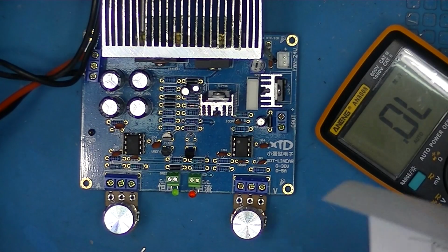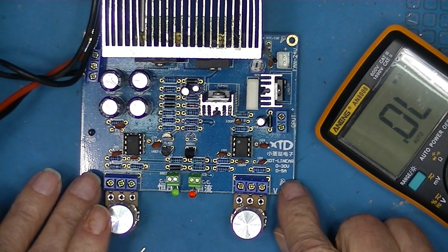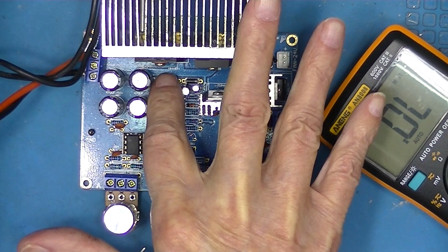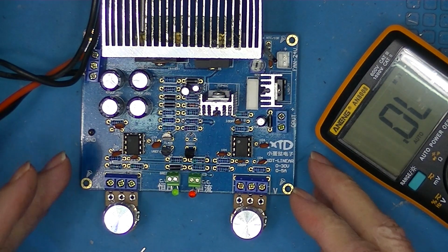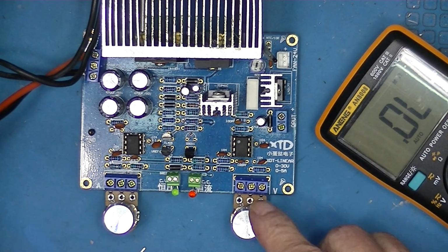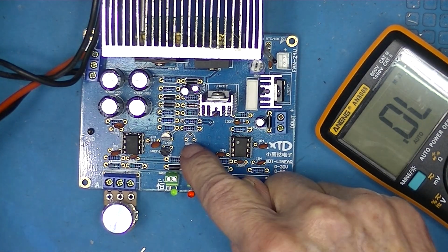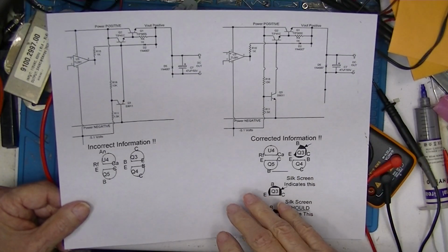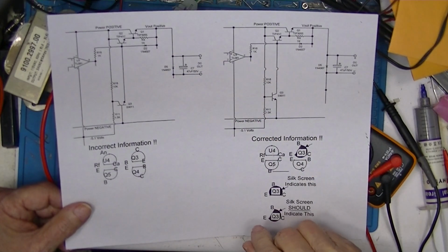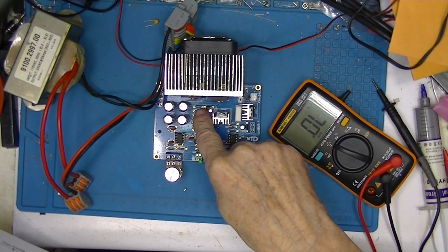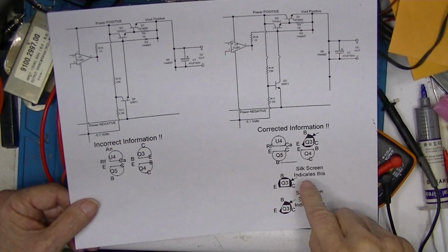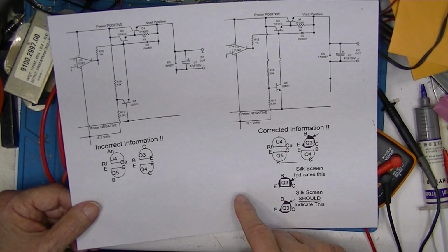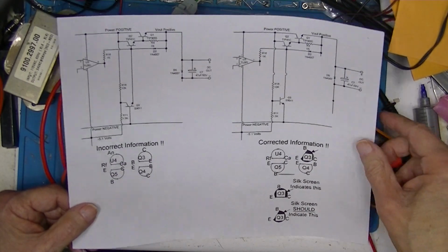Now I should say there's no revision number on this board. There is, I believe, to be a board maker number there. So if you get one of these boards, you'll have to check out Q3 with an ohm meter. I'll label this little notes. I'll put the board number of the incorrectly marked board. You could have a later or an earlier version. And I'll include this in the infamous subdirectory noted below.